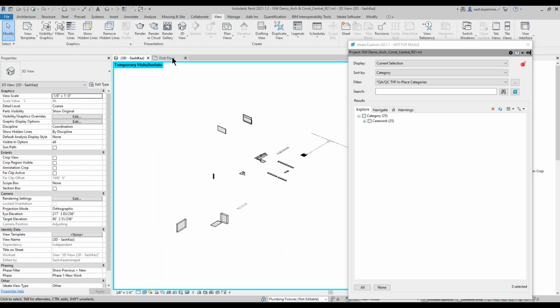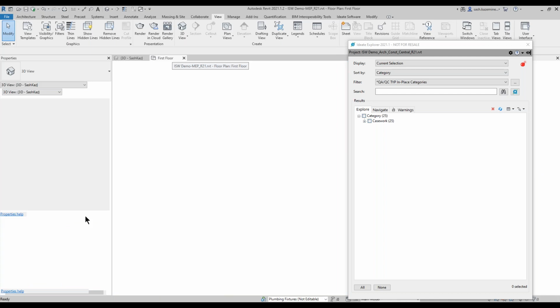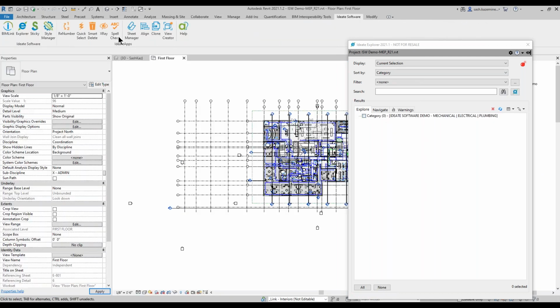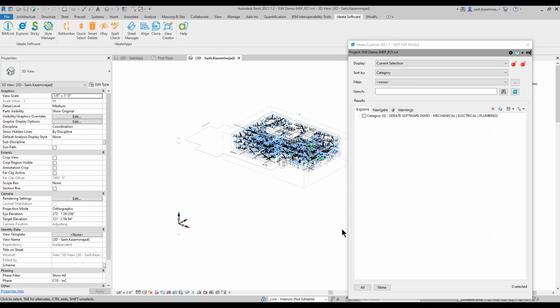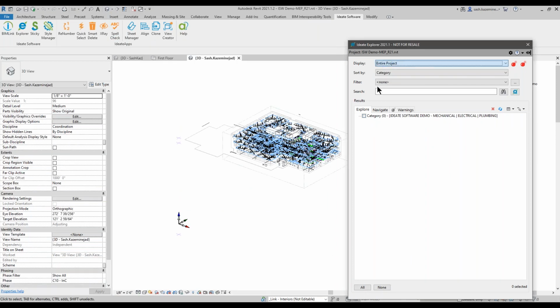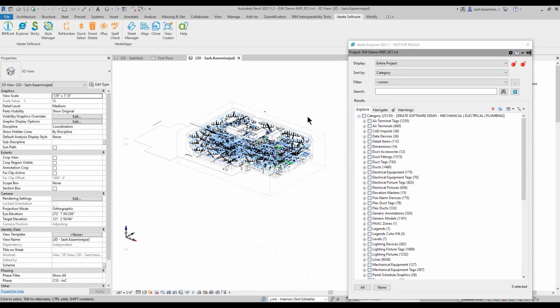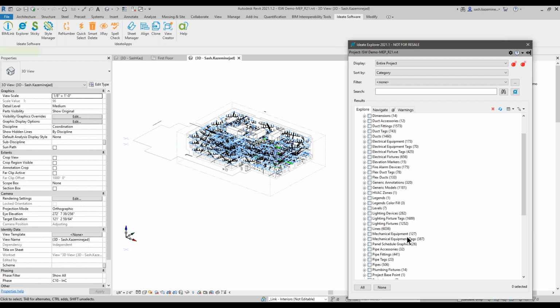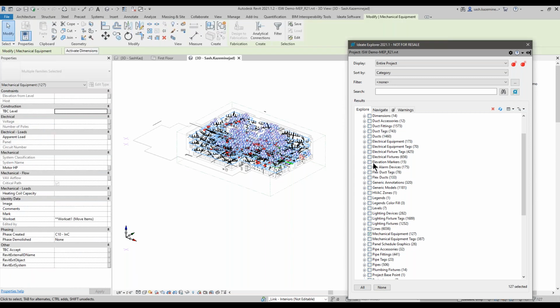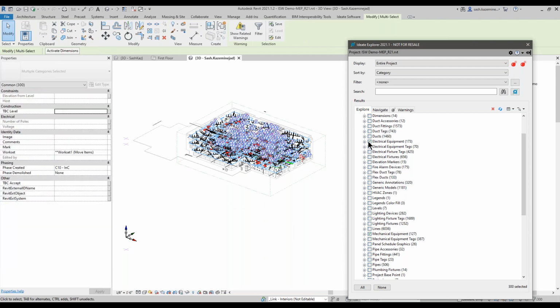Okay, and then just the last part I want to show you on the MEP side of things. I don't know if any of you MEP folks have run into this before, but what I want to point out to you is there are times in which people specify mechanical equipment, they download the manufacturer's equipment, they bring it into the model, and then they flip it. And that's bad, right? Because it may be designed to be installed one way, but now what happened was somebody brought it in and flipped it and did the design based on equipment that actually doesn't exist.